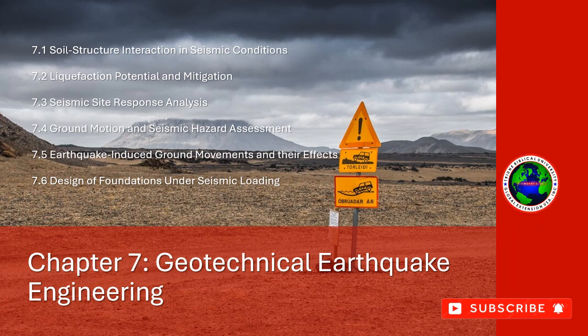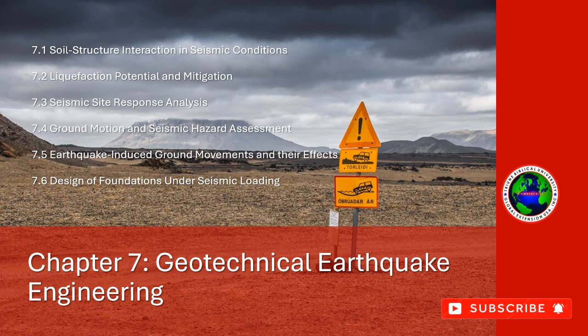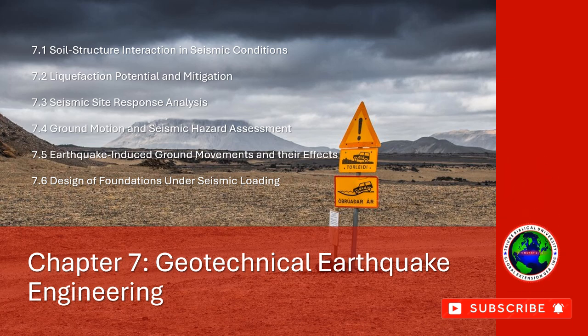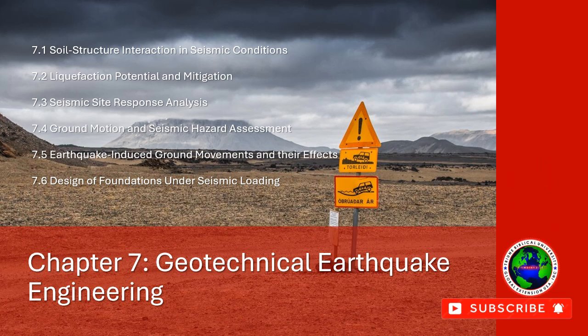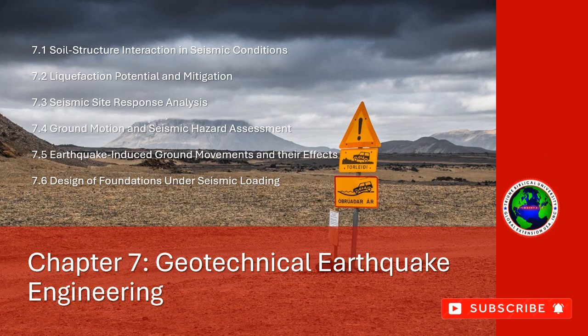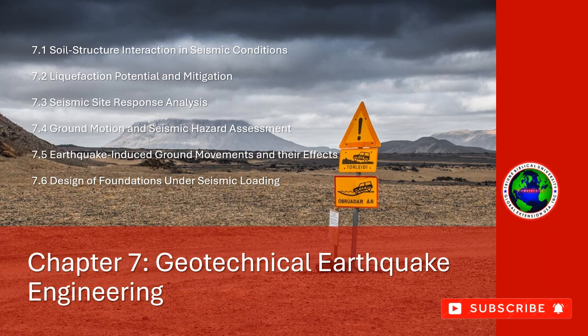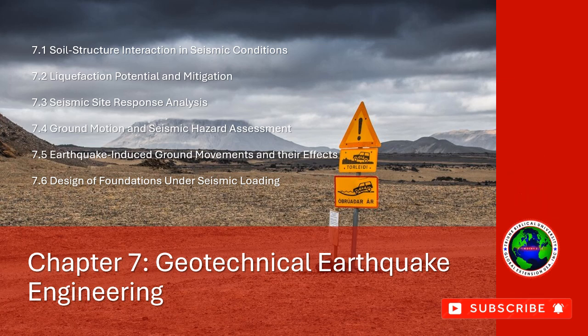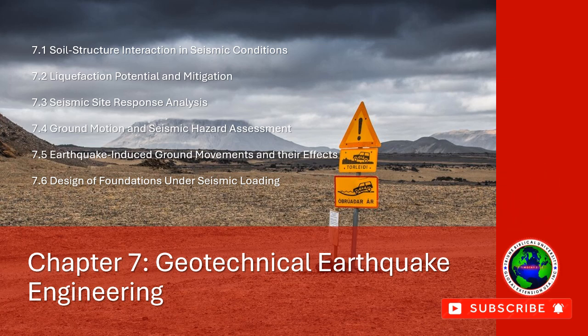3. Pipeline and utility disruptions. Earthquake-induced ground movements can cause pipelines, sewers, and other utility lines to rupture or displace. Horizontal ground displacements, in particular, can lead to significant deformation or breakage of pipelines. In areas prone to surface rupture or liquefaction, utilities may be cut or damaged, leading to extended outages and disruptions.